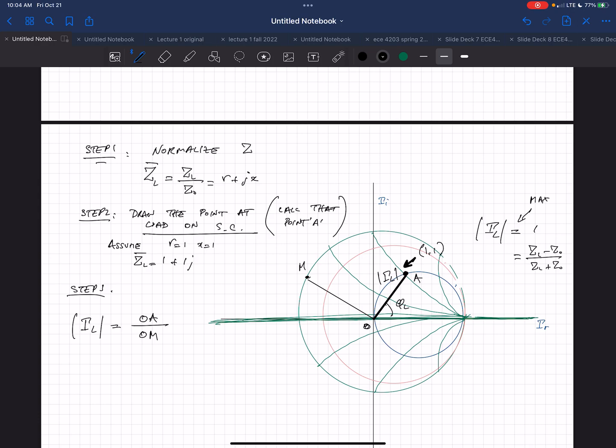So got to remember this is a graphical tool, and the first step in the graphical thing is that when you draw the impedance point, you can read the amplitude reflection coefficient just from where that is. Does that make sense? Just measuring this distance, you don't have to calculate what it is. You can get that value.